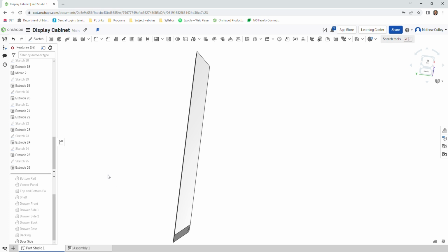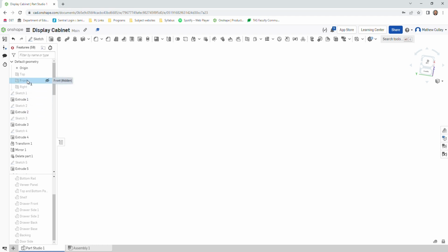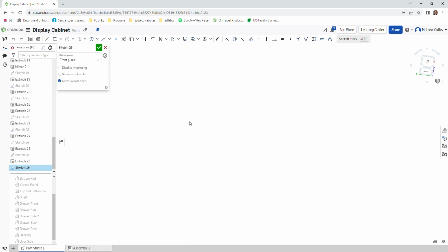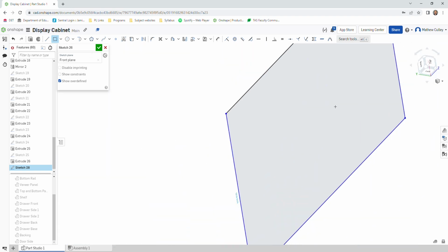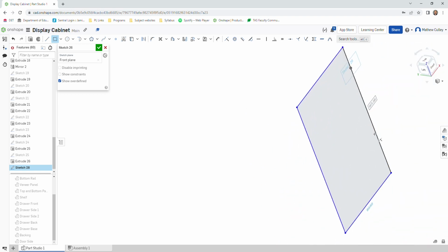and that's going to be our door top and bottom. Okay, so I'll hide that side, come back in, select the front, left click sketch, G for rectangle. Okay, I just need to orientate my drawing here. It looks like I'm on the wrong side. There we go.